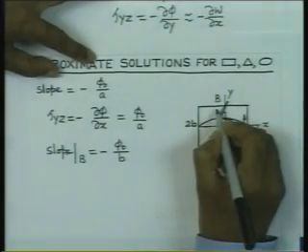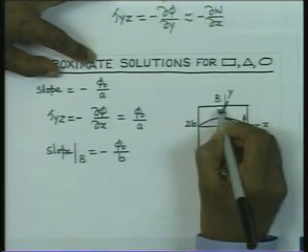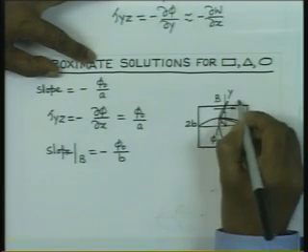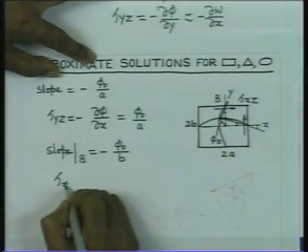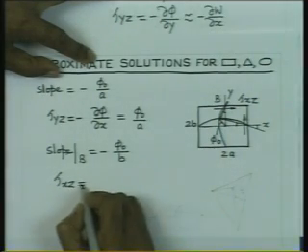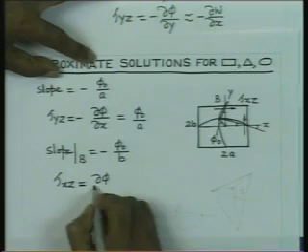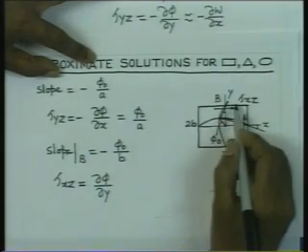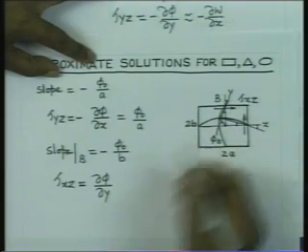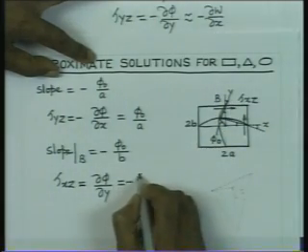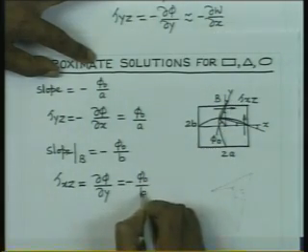The stress which is going to act here is parallel to this boundary, and it is nothing but tau xz stress. So, tau xz is equal to delta phi delta y, and we have found that this slope which is given by this angle is nothing but minus phi 0 by b.